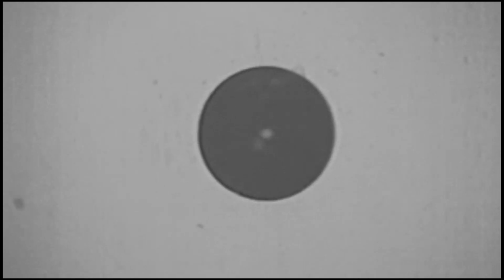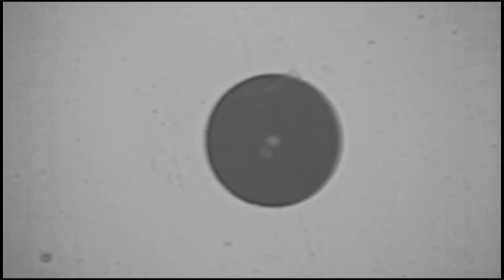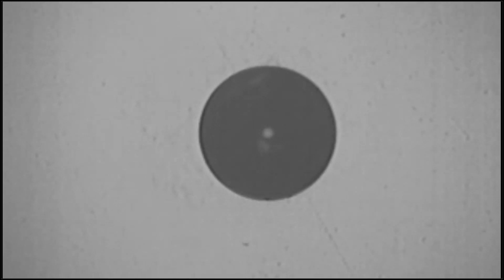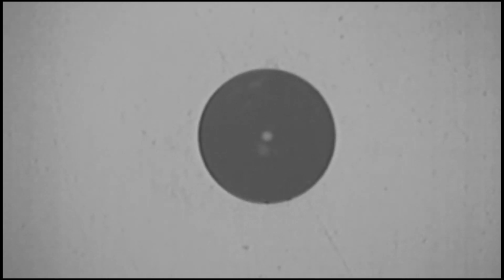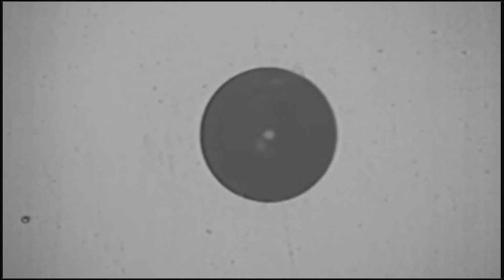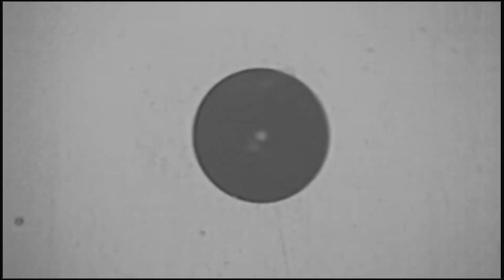Let me wipe that down real quick. That is a polished connector. It's one I use regularly, so it might be a little scuffed up. The tiny little dot in the middle is your business end. That is your 9 micron. The rest of that's 125 micron core plus epoxy. The white stuff on the outside is the zirconium. So as you can tell, it don't take much to mess that up because it is a very small aperture.